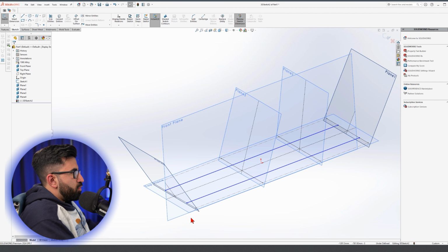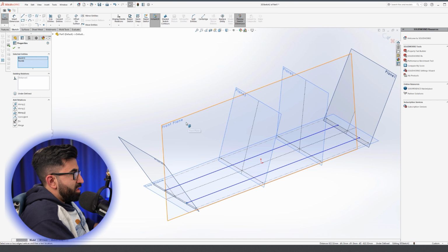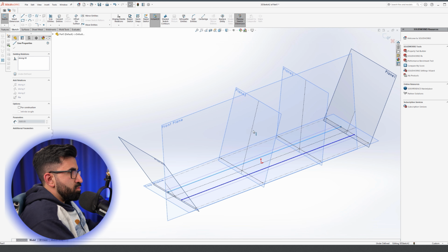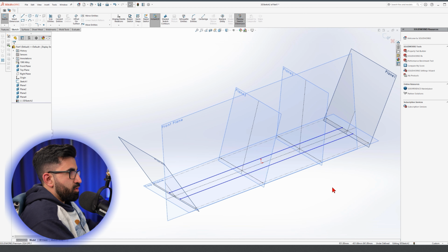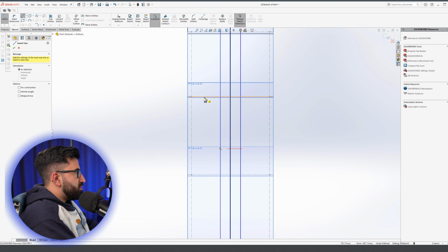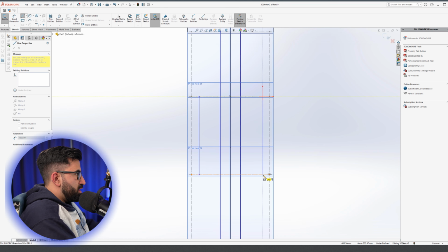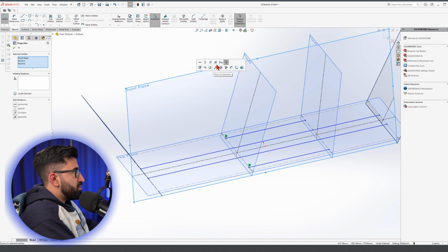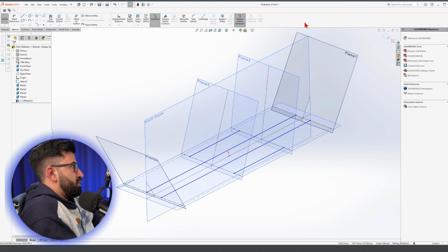Same thing here. Now, what do I do? I hold the control key down, select these 2 endpoints and the front plane, so I can click on make symmetric. This way, these 2 lines work symmetrically according to each other. Now going back to the top plane again and draw the other 2 horizontal lines for the cabin part. We need to make these 2 also symmetrical. Control and the front plane symmetric. But continue with the modeling.